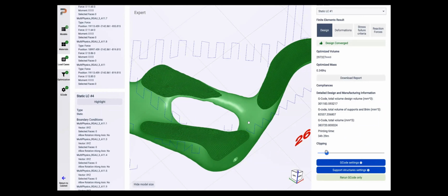Should I give some more information on that? Yeah, please, Inga. Sure. What we did so far is that we changed the rotation within the software and did a whole 360-degree rotation study, let's call it that way. We have the opportunity to export a report of the different values of compliance and stress, etc., of the resulting model of the optimization.